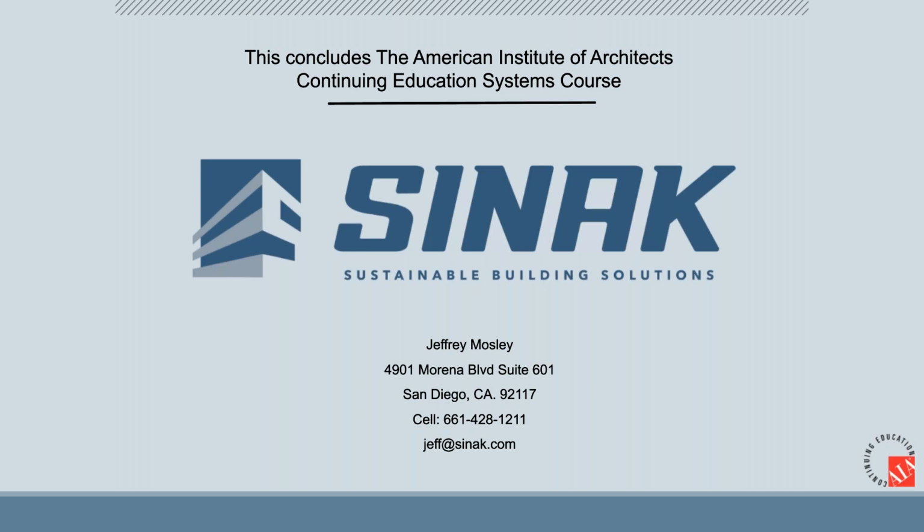This would probably be my favorite question in the world. As a member of the F6 committee, F710 is a practice. It is not a weighted test method or specification. It is designed as the minimum guidelines for a flooring contractor who has no prior knowledge of the concrete's condition or abilities to perform, so that he has a basis to work off of to ensure he's not held liable for his problem. I mentioned earlier about urethanes.